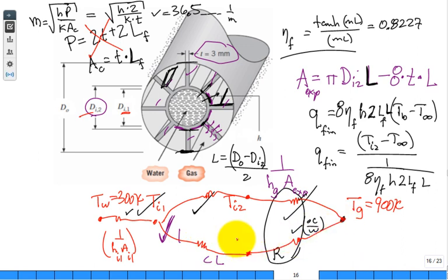And so this would be the temperature at I2 under the fin, and this would be the temperature I2 exposed, no fin, if you think they're significantly different. And then this would be conduction just through this, and then you have the convection on the exposed, and then you'd have conduction through here, and then you have out through the fin. Don't do it that way. Do it the way I showed you, okay?